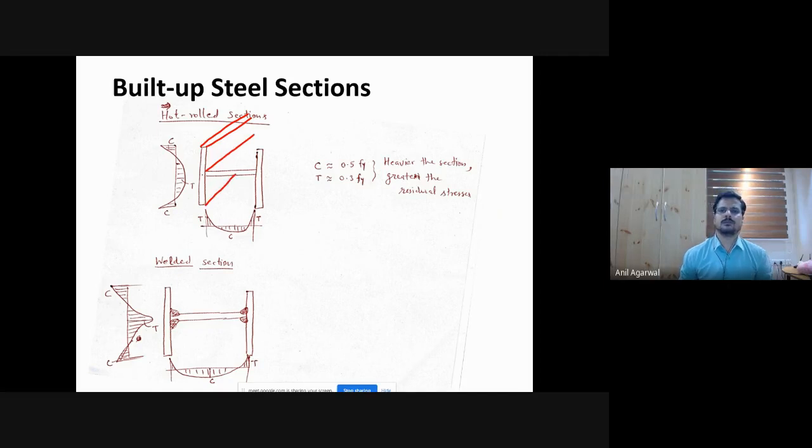Okay, so let's say this is the flange I'm looking at, and these are the different locations. What will happen is that this portion will be in compression, and this portion will be in tension. So that is this portion of the flange. At this surface, it will be pulled into this, and there it will be pulled like that by the rest of the beam, the rest of the flange. And this one is pulling the other way.